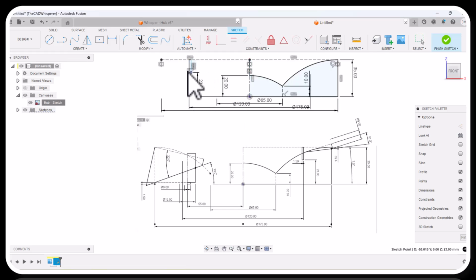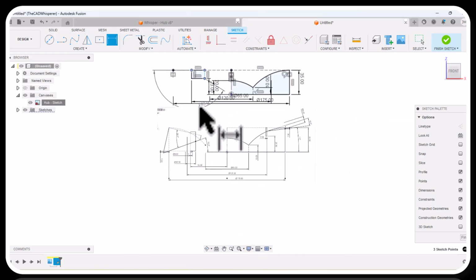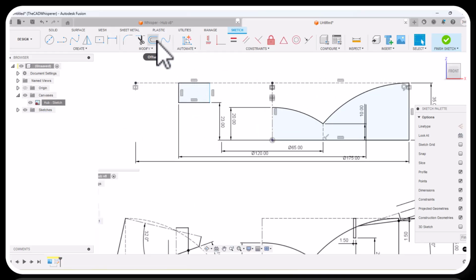I see this is still blue, so when something is still blue, drag it. It's obvious then I need to put the width on that. So I'll dimension the width of this, and I might put it down here, or I might put it up here. I'm going to put it up here. And actually I got that as an angle line, so let me try that again. I'll select those lines. Instead of this point and this point, I'll select this line, and I'll do that as